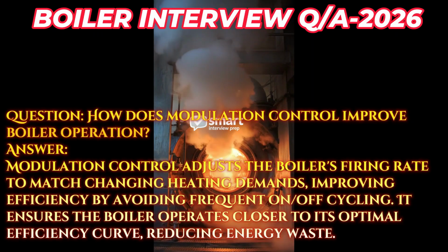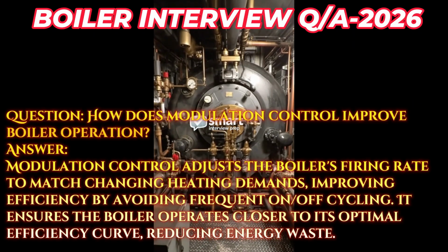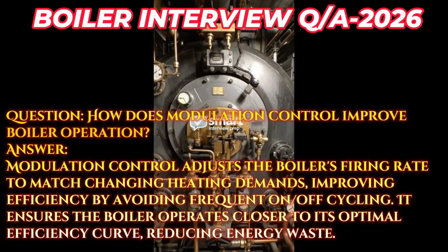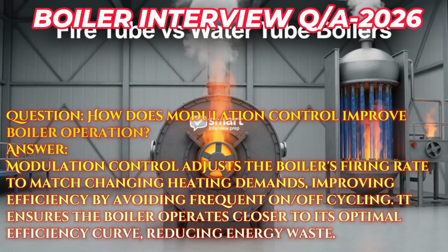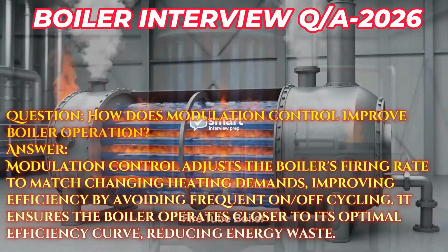Question. How does modulation control improve boiler operation? Answer. Modulation control adjusts the boiler's firing rate to match changing heating demands, improving efficiency by avoiding frequent on-off cycling. It ensures the boiler operates closer to its optimal efficiency curve, reducing energy waste.